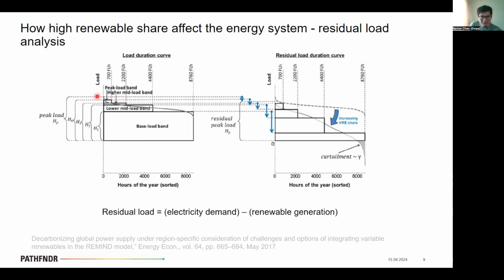And you can see in one year you get one very high peak load. In Europe, that probably happens on the cold winter days when you have high demand. And if you sort these numbers, the lowest point usually could be on a day that doesn't have too much heating or cooling demand, and probably the holidays, so the demand will be low. But usually, this curve helps us understand first what the peak load is, and second what the minimum load or base load is.